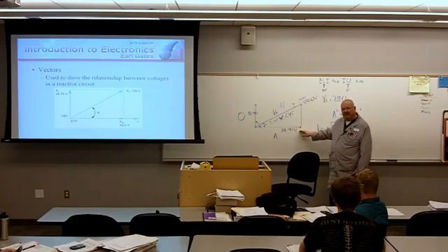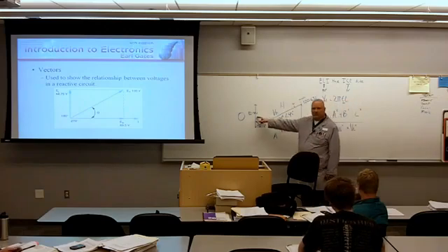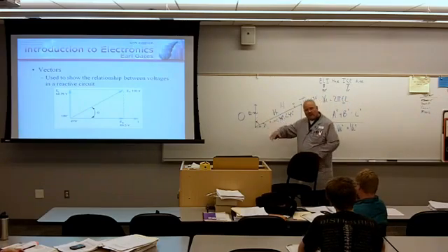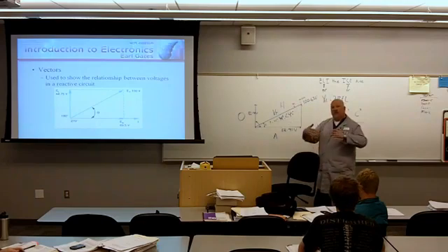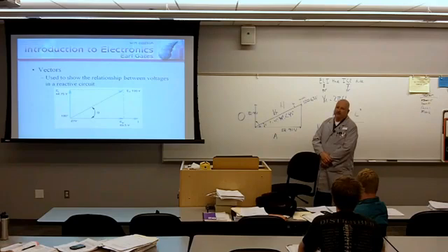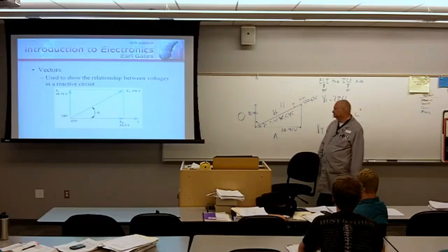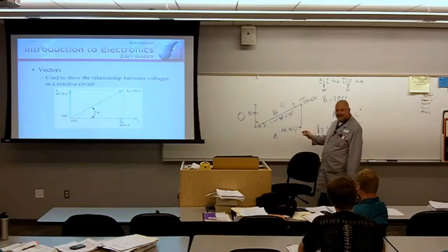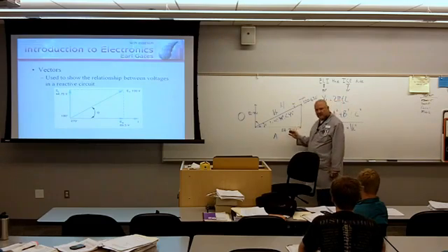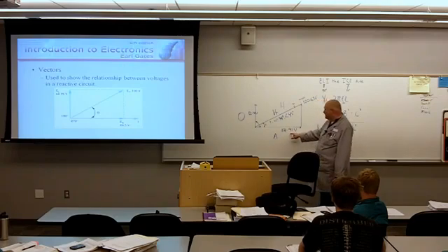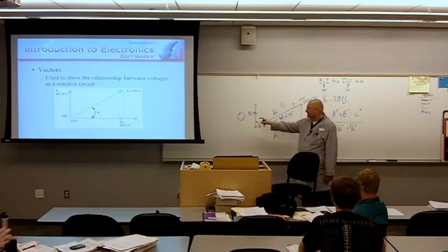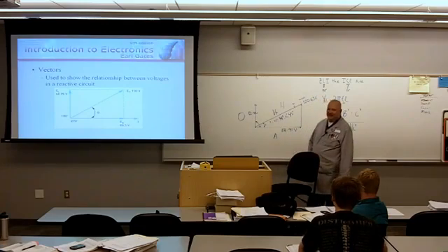This 90 volts is occurring at a different moment in time than this 45 volts. So when asking for VT, we're looking at what's the cumulative overall effect in the circuit. Does that make sense? Okay. We could also do impedance this way. And in doing impedance through this method, it's going to be the same thing. Well, if we're getting a bigger voltage drop across the resistor than we are across the inductor, what does that tell us right off the bat?